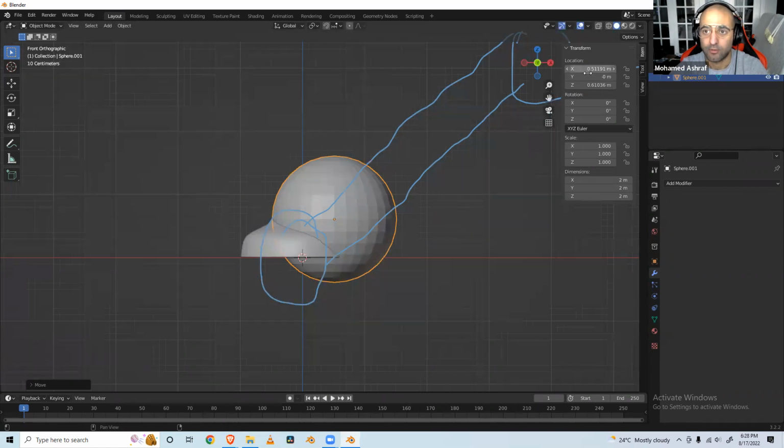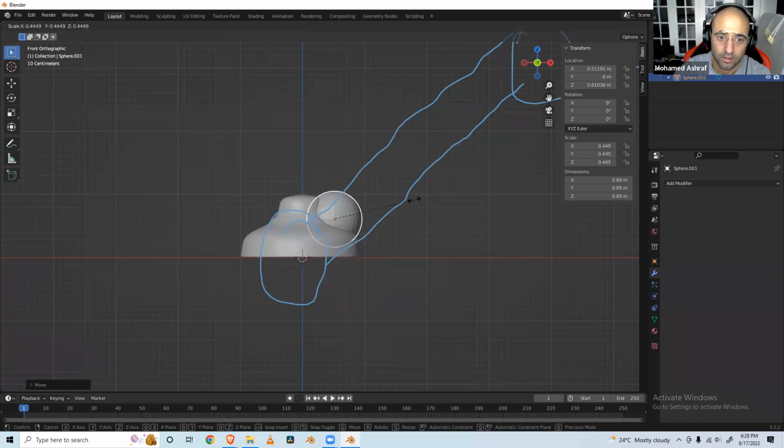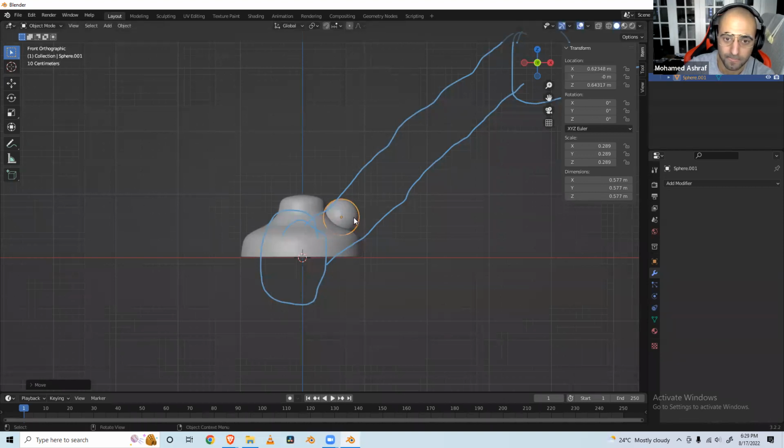And you can find the transform tab here, and it shows you everything you need to have. It gives you a lot of granular control over the X, Y, and Z coordinates, the rotations, as well as the scale and the dimensions. Dimensions are incredibly useful if you have something like a technical drawing, or if you're making a feature or a product or a component that's supposed to fit into another part. So let's scale this down. And you can tell this is very heuristic in nature, just by the mere fact that I'm going based off looks, based on how I feel, how this looks.